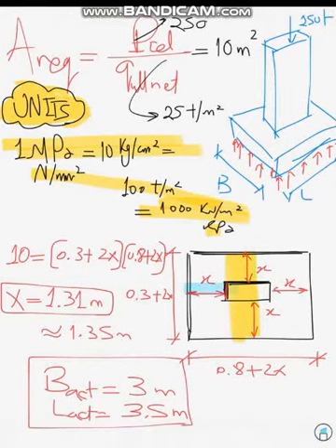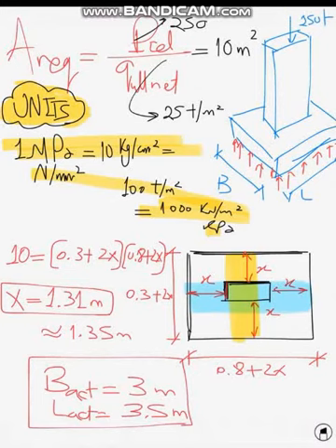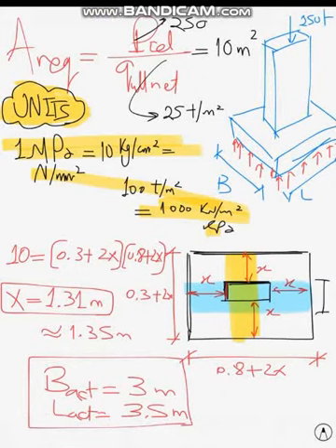It doesn't matter in the design of isolated footing if you take a strip in that direction or the other direction, because the extension of the foundation is the same around all sides of the column. So there is no difference between the two directions. Each one will have the same straining actions. This is a strip 1 meter, and this is also a strip 1 meter.